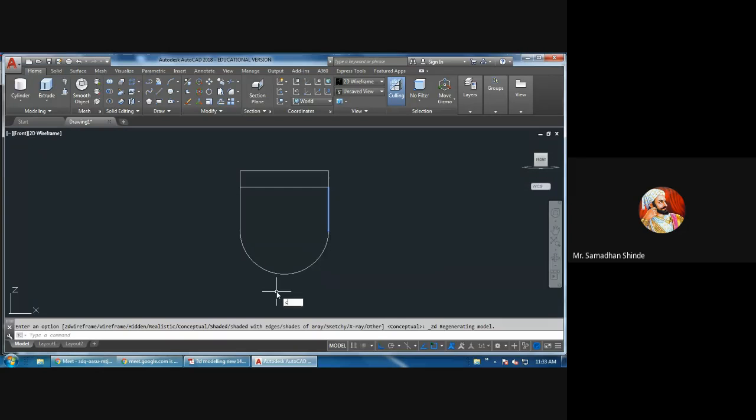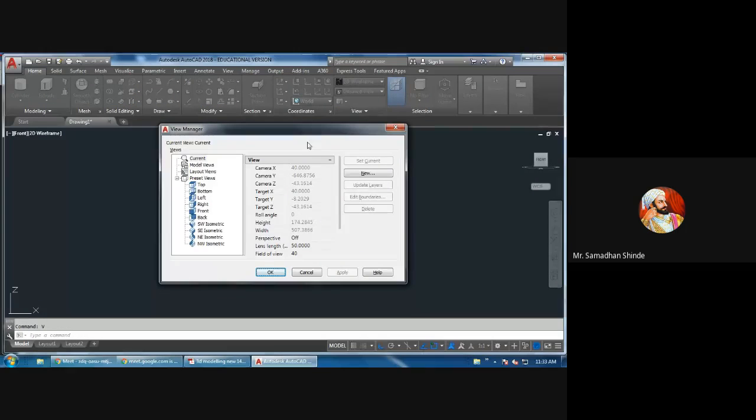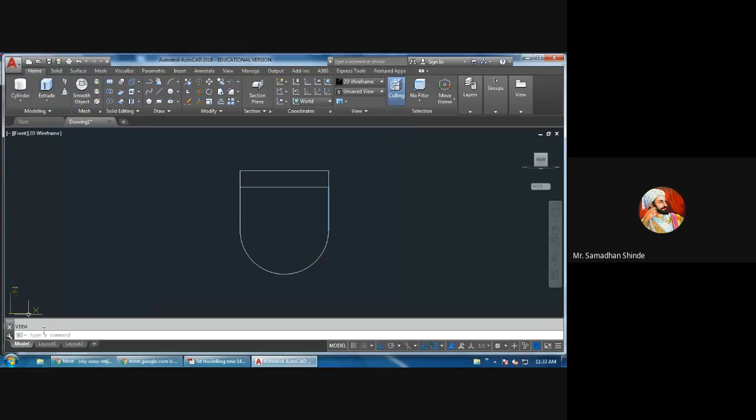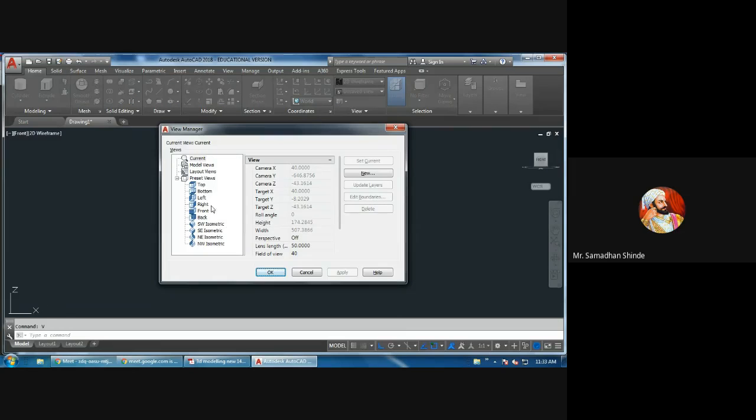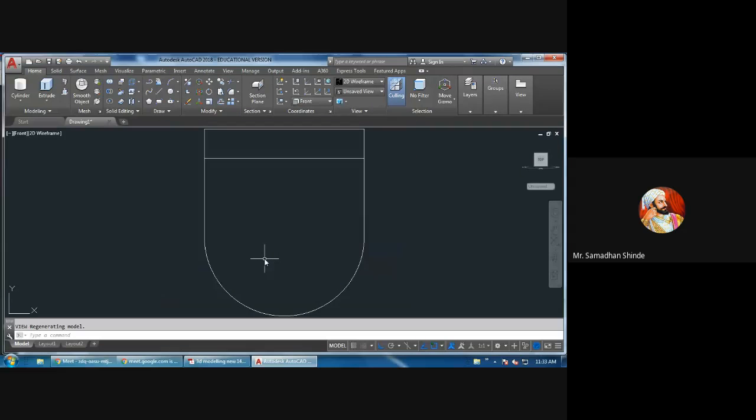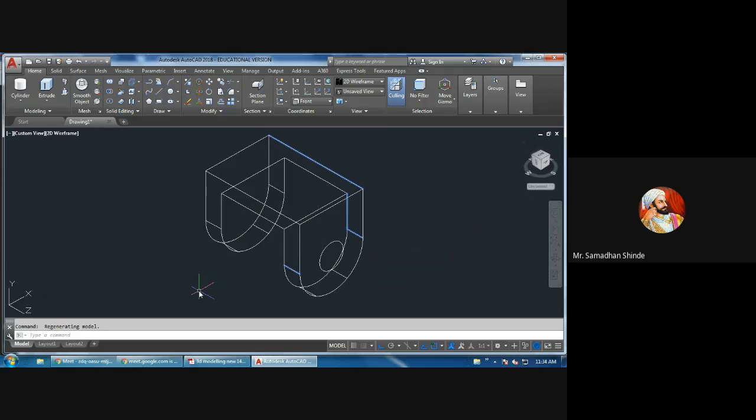So what I will do, I will draw. Before that, this front direction, which is this plane, my direction of plane is zx or xz. Here we cannot draw anything. So our plane should be xy plane. So we have to convert it into xy plane. Front, okay, enter. From this center, circle, enter diameter 30 like this. Then here we have to extrude this now.